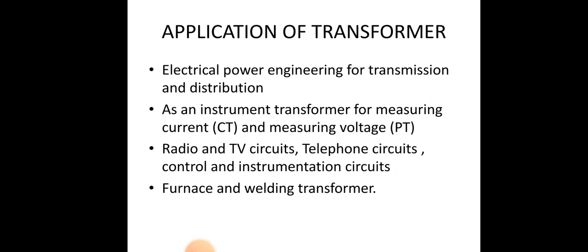The transformer is used in electrical power engineering for transmission and distribution. So we have transformers used for transmission purpose and distribution purpose. In transmission and distribution, we use a step up transformer or step down transformer depending upon the requirement. And next one, as an instrument transformer, it is used for measuring current and voltage. For measuring current, we prefer a current transformer. For measuring voltage, we prefer a potential transformer.